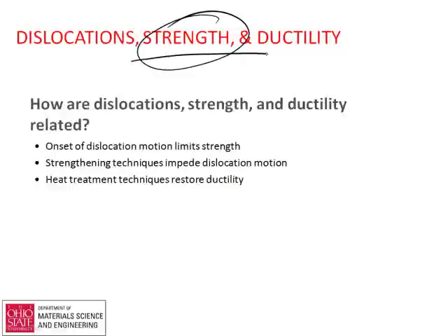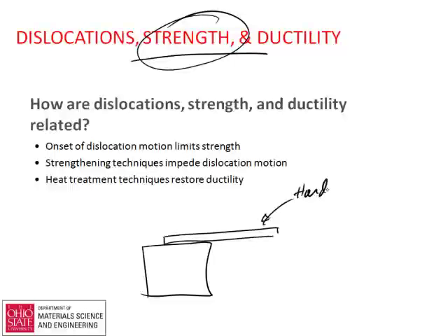A simple demonstration I mentioned last time that you could easily do to show this sort of thing is, for example, you could get some hardened aluminum, and you could buy this from McMaster-Carr, McMaster.com. You could look at what they call shim stock, and that's full hard aluminum. You could do this like a diving board and see what the stiffness is. The stiffness of aluminum is about a third of that for steel, for example.